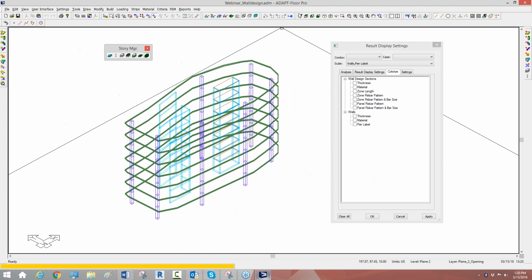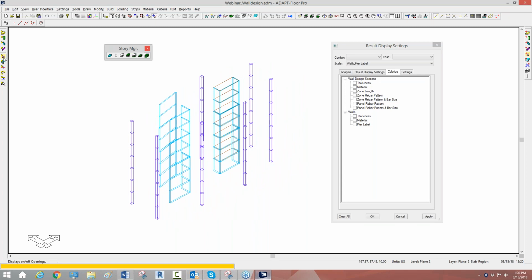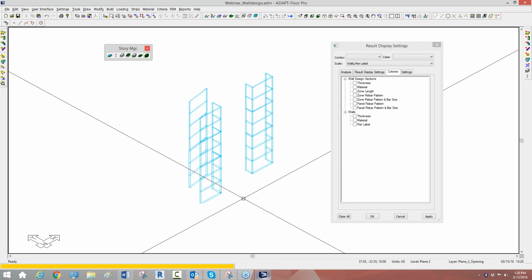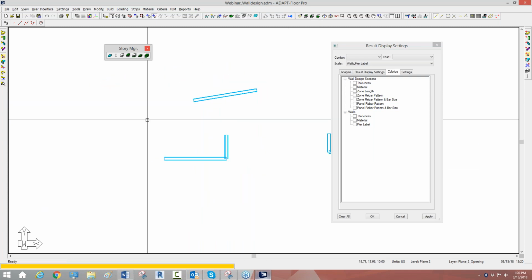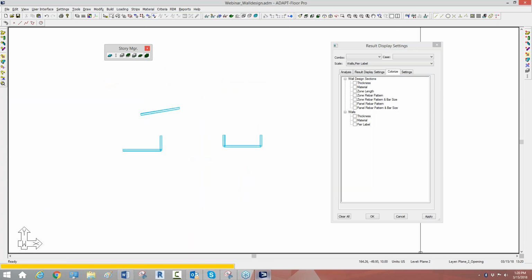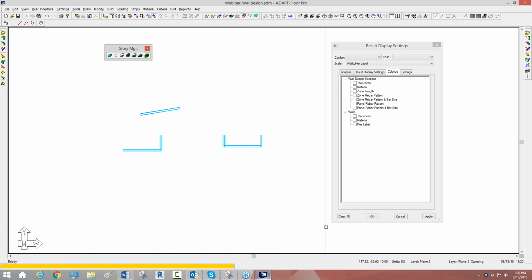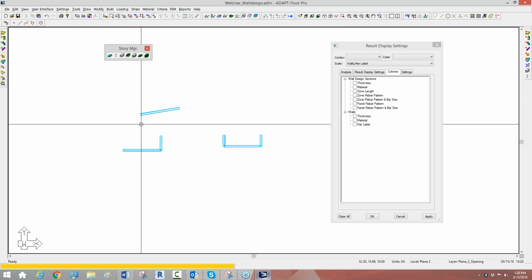So I was mentioning before the question that in order to design walls, you have to define piers. So we're going to go ahead and I'll go to a top view. Notice that I'm in global mode, and I'm going to select and define piers.